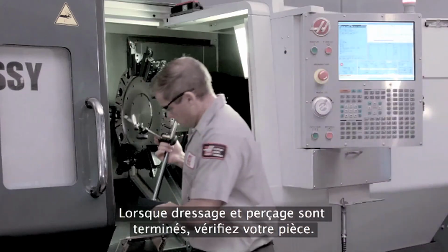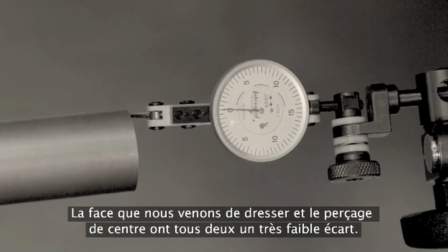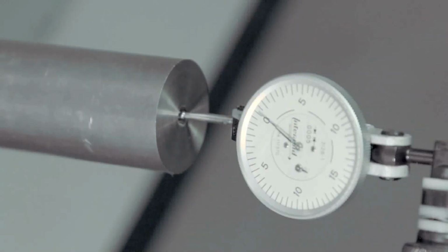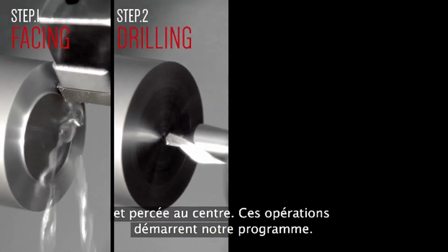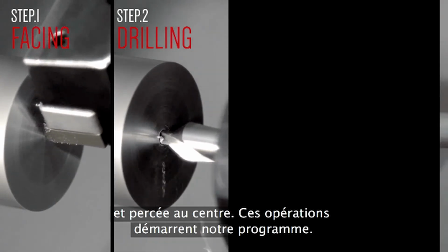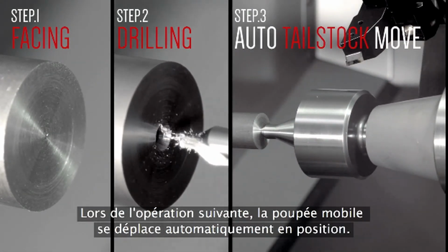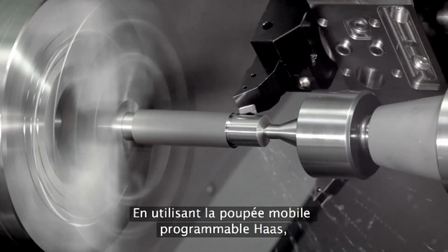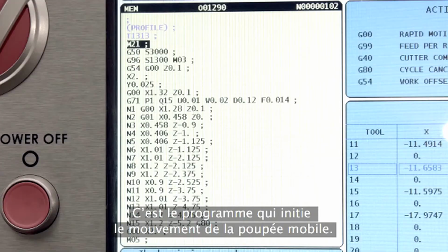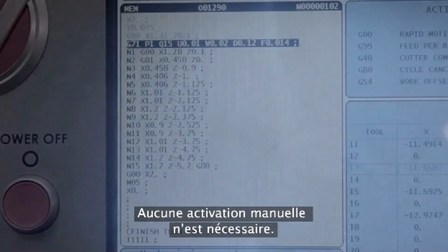With the facing and drilling complete, let's check our part. Both the face we just turned and the center drilled hole have very low runout. Great! Okay, so we just saw the part get faced off and center drilled. These operations start off our program. Next, the tailstock moves automatically into position. With the part supported, the cutting continues. Using the Haas programmable tailstock, motion is initiated from within a program. No manual activation is needed.